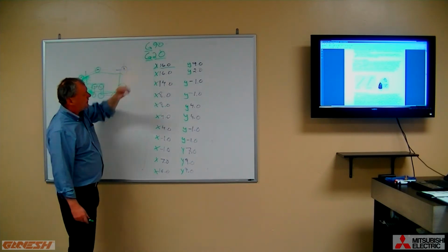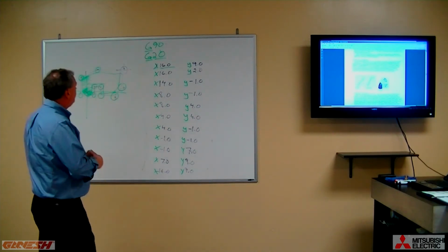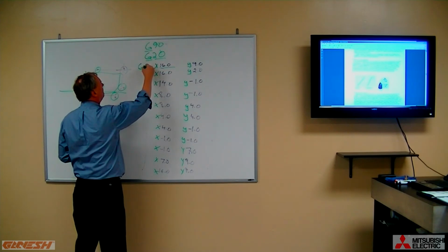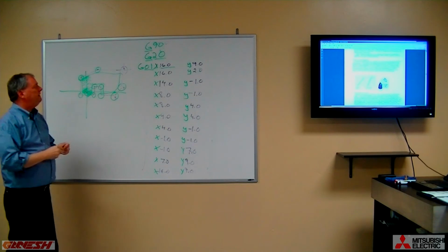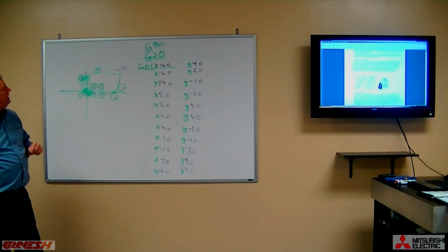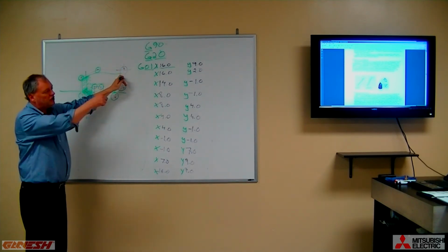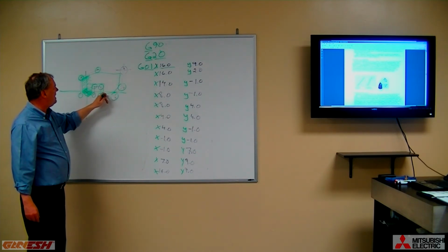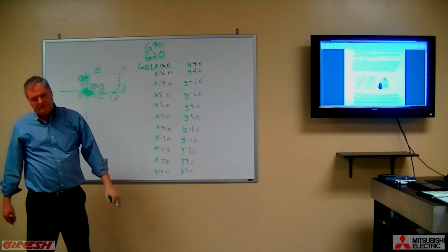So another preparatory function that we'll introduce you to is called a G01. G01 says that we want this to move at a predetermined interpolated feed rate. We want you to move the same rate and the same distance for each axis, and we want it to be slow and easy as opposed to very rapid or very quick.